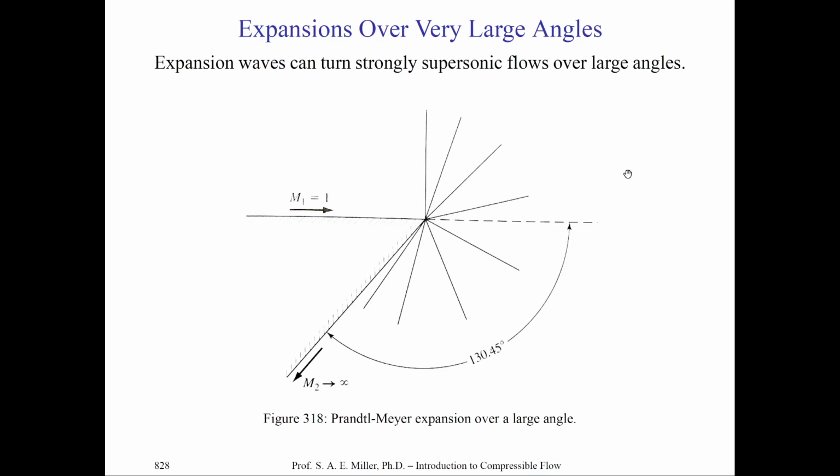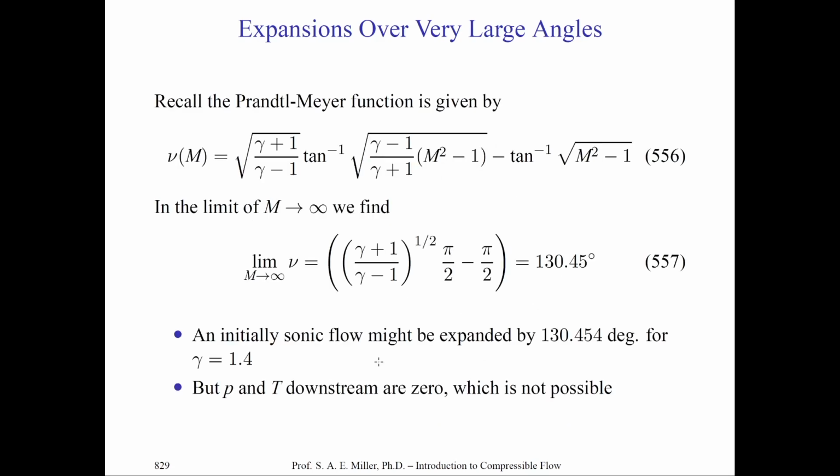It's very unlikely that you'll have this nice attached flow over a large angle. But indeed, the pressure gradient is in your favor, and therefore it's very likely that the flow wants to be attached. And so, through Prandtl-Meyer expansions, you can have rather aggressive angles and keep the flow attached for many situations where you would think it would not occur otherwise.